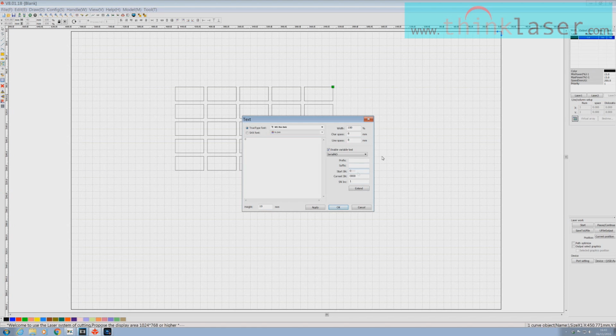Start serial number. So if I choose to put the start number at, for example, just 1, because that's where I want to start, I don't want to start it at 0, then what will happen is it will only go to 9 and then it will roll over to 0 and back to 9 again. I will only get 1 digit. Therefore I must make sure that I use as many digits in here as I need for my maximum serial number. So let's go 001. Now that will allow me to go up to 999.